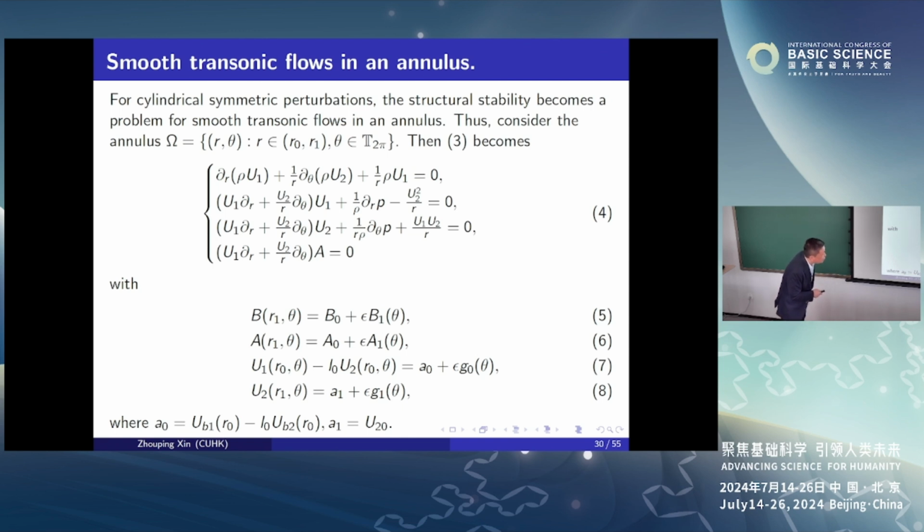But for R0, what is this? This is a flow angle restriction. You see, this is a relation between the two components of the velocity, one in the angular direction, one in the radial direction. This tells you there is a restriction on the flow angle with which the flow comes in. So this is a physically acceptable boundary condition. This one is on the exit, okay?